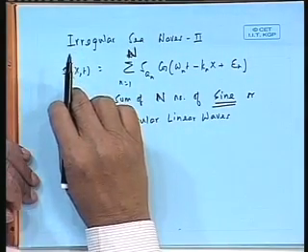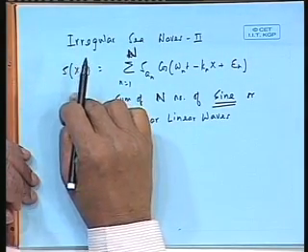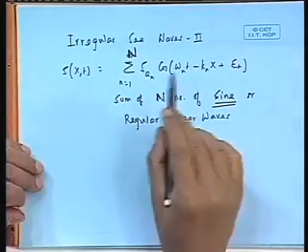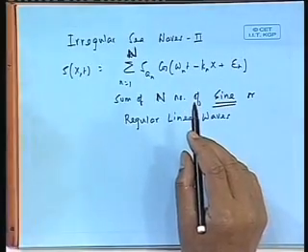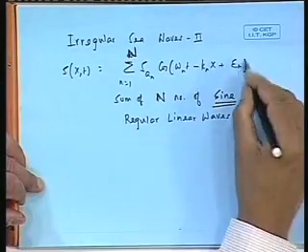In other words, the random signal that we had could be broken down into n number of sine curves, each of them representing a small amplitude regular wave with a random phase.